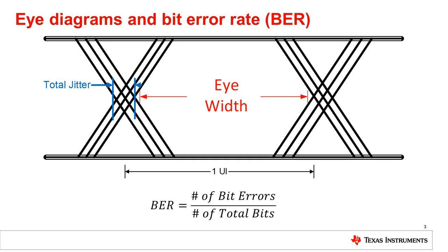Bit error rate is useful in discussing the overall fidelity of a given data link. BER describes the probability of bit errors occurring over a set amount of data. Bit error rate is calculated by dividing the number of bit errors by the total amount of bits being measured. BER is expressed in scientific notation where only one bit error is allowed for the total number of bits measured. This unitless number is often used to describe the amount of data included in a particular measurement without error or at most one bit error.